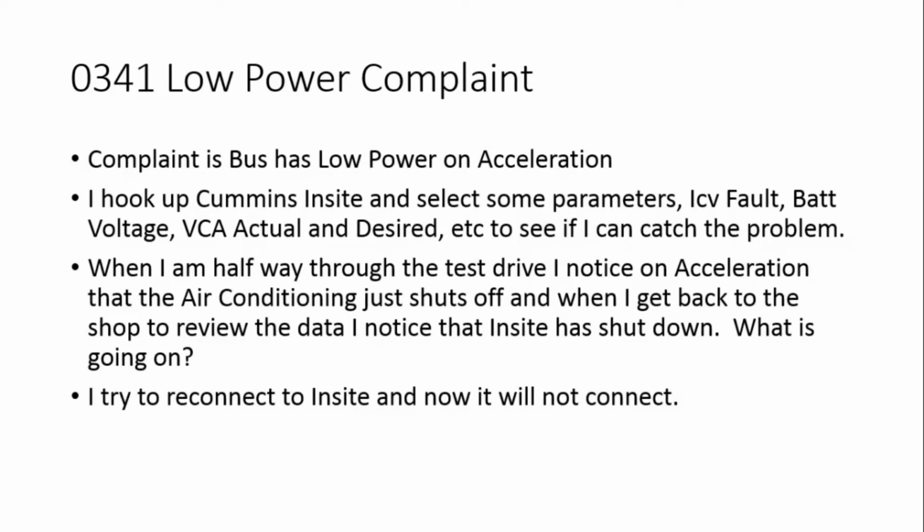So when I get about halfway through the test drive, I notice on acceleration that the air conditioning just shuts off. And when I get back to the shop to review the data, the software shuts down and I don't have any data. So now I'm like, okay, what's going on? I tried to reconnect and it still won't connect. I thought there was something wrong with my interface, so I tried another bus real quick and it worked fine on the other bus.